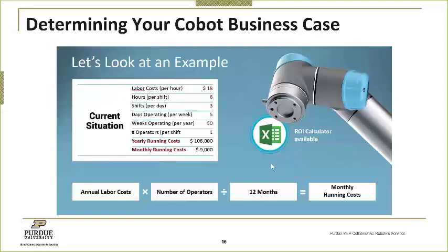Of course, additional things like grippers, vision systems, and other systems you want to integrate with that robot will add to the cost of the deployment. So the rule of thumb that I use is about 2 to 2.5 times the purchase cost is what you'll typically end up spending on the installed costs for the robot. So take the purchase price multiplied by 2 or 2.5, and you've got a ballpark number for a total installed cost. Again, it depends upon how much you want to do in terms of systems integration. It could be higher than that if you have a lot to integrate.